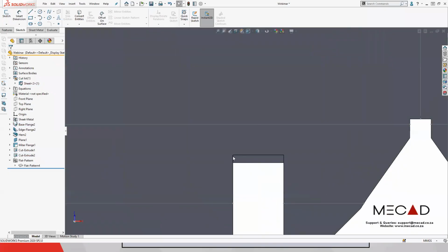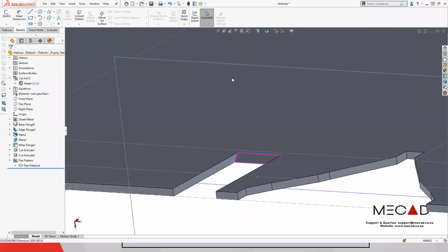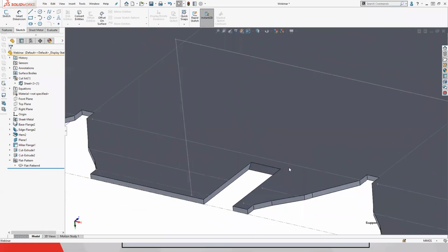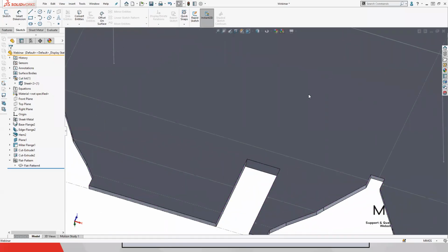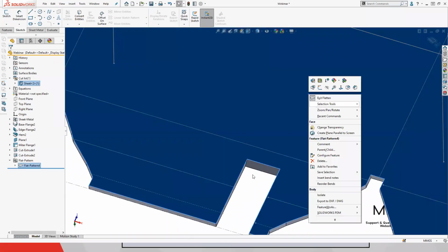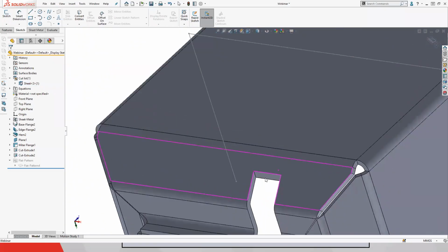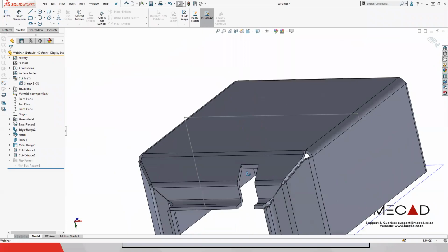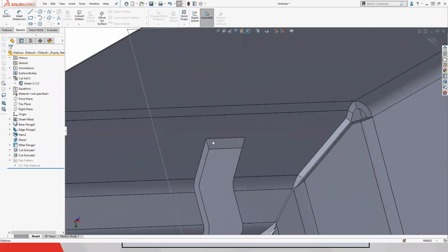you'll see now it gives me a flat pattern, and this face is at an angle. This doesn't work well for production purposes when you send out your component for manufacturing, especially with the plasma cuts and laser cutting. You're going to struggle with that face. So it would probably have to be redrawn. Or what I've also noticed is we actually get individuals or CAD designers who actually go and do a cutout at an angle. That's not necessary.